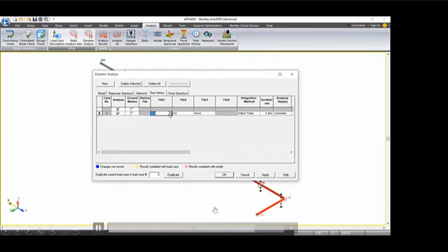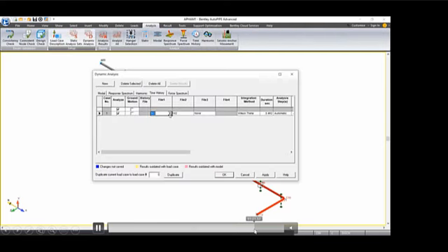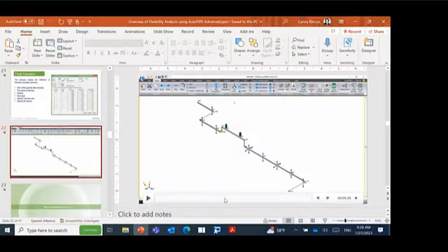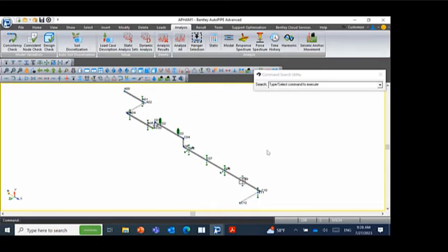But the important thing here in fluid transient is that you define the load, okay, and you can define the load in dynamic analysis because it's more dynamic. Remember, in AutoPIPE, in analysis, we have several types. We have dynamic, we have static, and we have modal, okay?